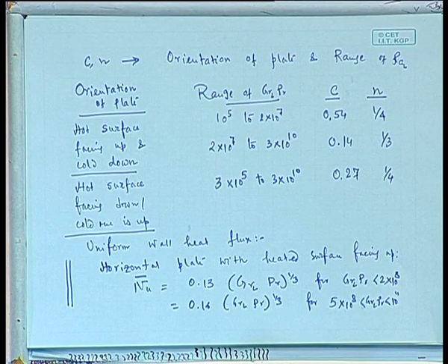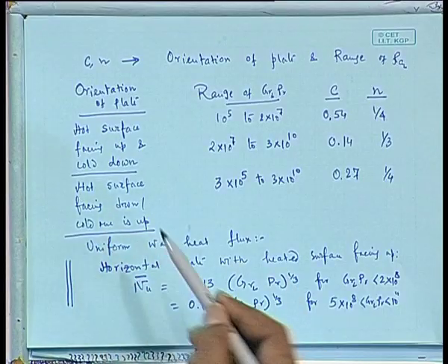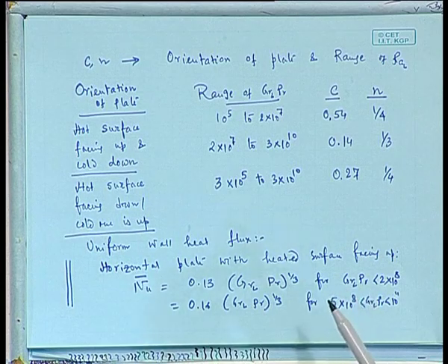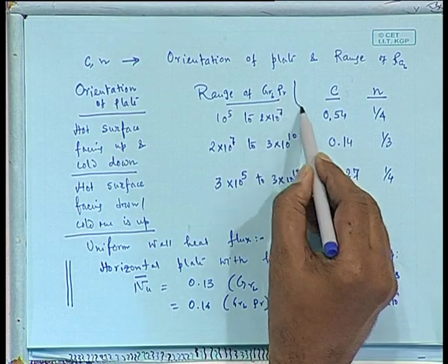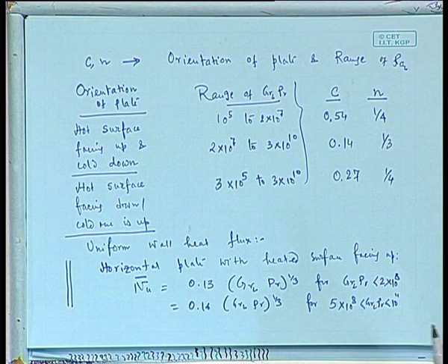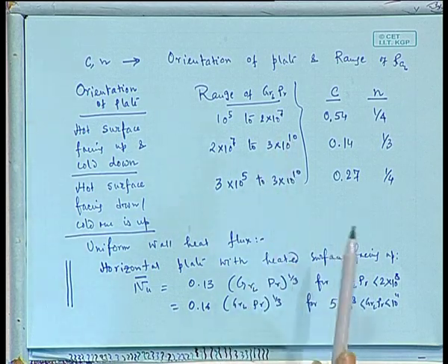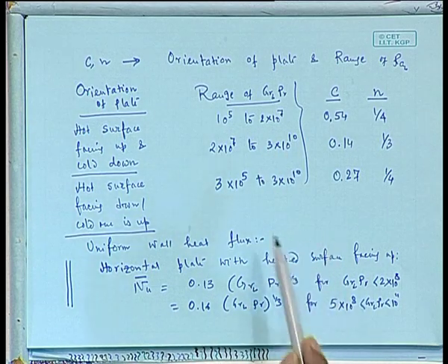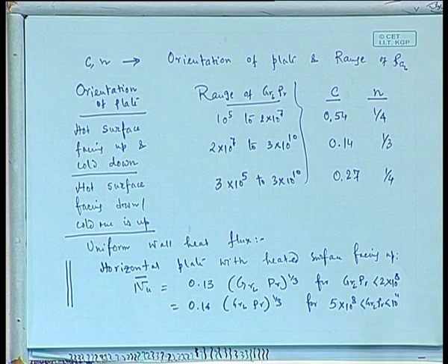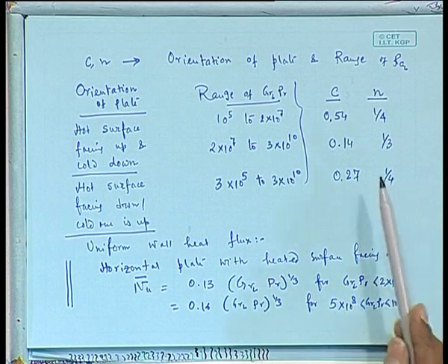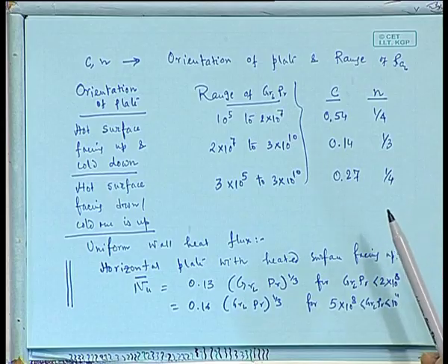So for a particular problem, you have to identify the condition, orientation of plate, geometry, and then calculate these values. Like you calculated Reynolds number to find out whether the flow is laminar or turbulent, similarly for this case you have to calculate this Grashof and Prandtl product. This is known as the Rayleigh number, and depending on this value you have to select a proper correlation with a proper exponent, to find out the heat transfer coefficient and ultimately how much heat has been transferred by free convection.